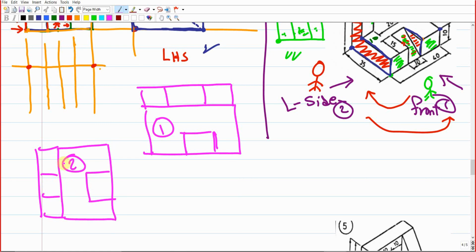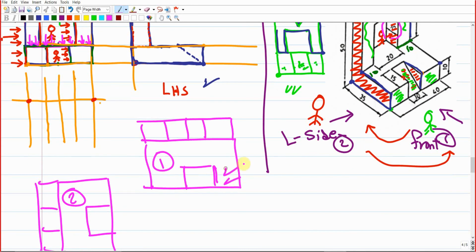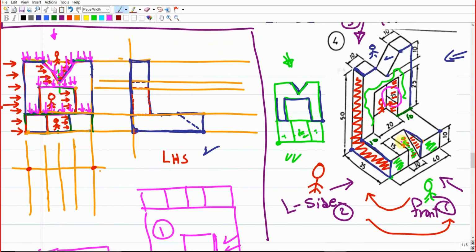Which one is correct? It means that this is, and there should be one line here. So this is the correct orientation of the top view, how it should look like. Why? Because if you just try to give rotation to this shape and you look at it from the top, you're gonna see this box should be on the right, this box should be on the left, these two inclined surfaces should be in the middle, this one will be directly in front of you, then you're gonna see in the middle the inclined surface, right? So let us create this one here.